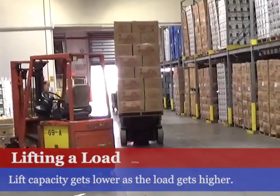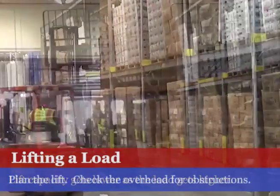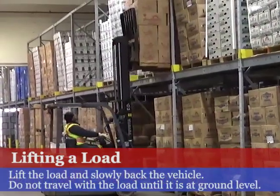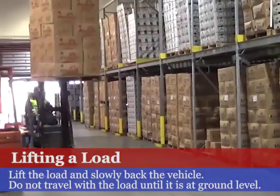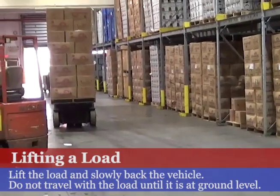Remember, as the height of the mast increases, the capacity of the forklift decreases. When lifting overhead loads, check for obstructions, such as lights or piping. Lift the load off the rack, and slowly back up the vehicle until the load is clear. Lower the load carefully. Do not move the vehicle until the load is all the way down.